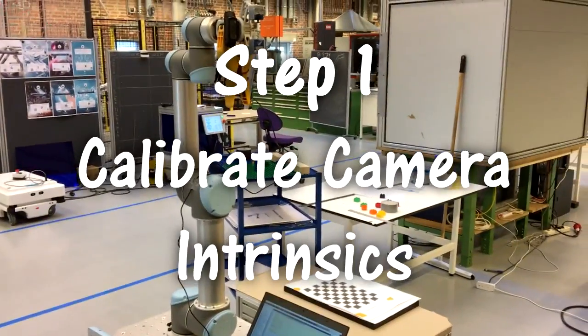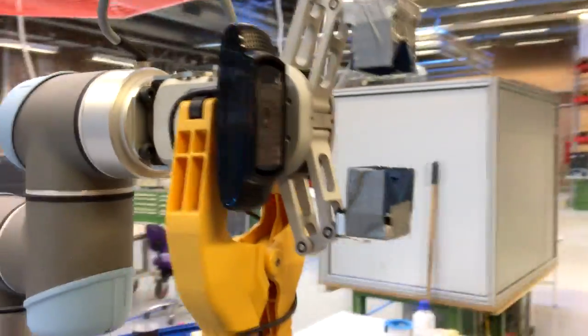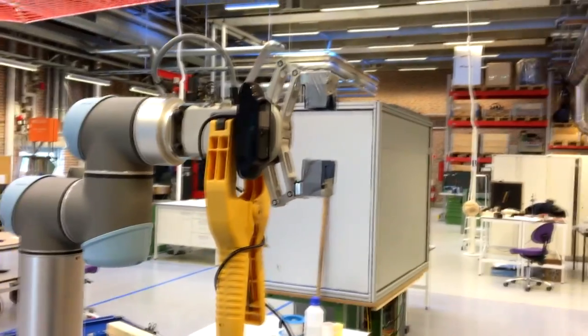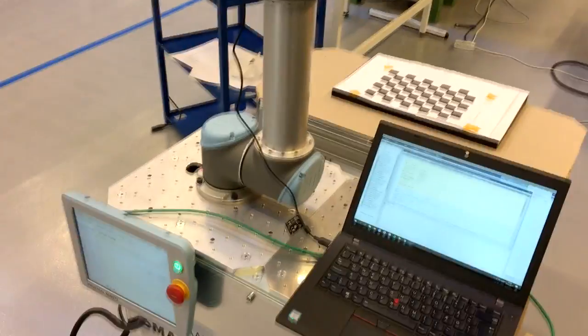The first step of the procedure is to calibrate the camera. We've installed the camera on the robot arm onto the gripper, which allows us to use the robot as a station frame to hold the camera above the objects. But we need to calibrate the intrinsic parameters of the camera, which is why we have implemented an automatic calibration feature.